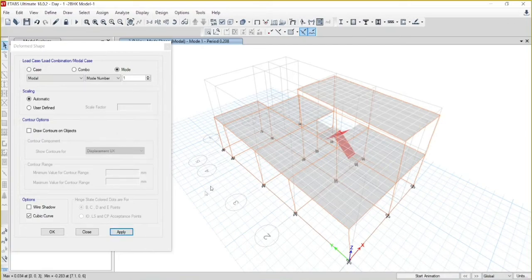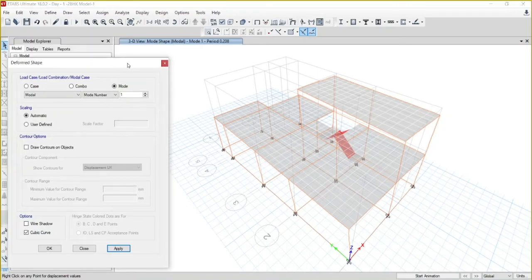Note here, when we are applying the modal analysis, you can check here the period has become 0.28, which we have analyzed by using a formula earlier. The time period is nearly matching 0.2. So the structure is having 0.2 of fundamental natural frequency for mode 1. Since you are having different modes, let us check the next mode.